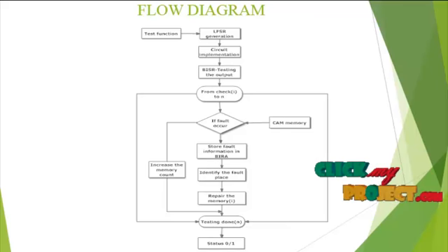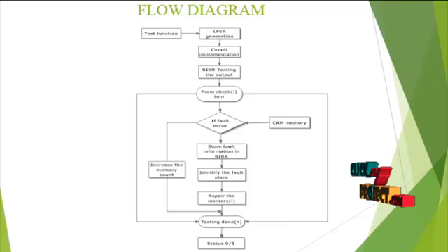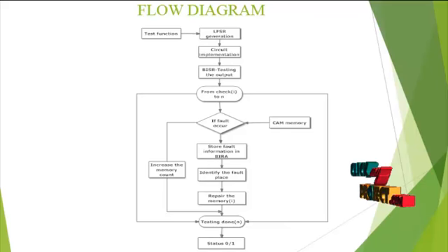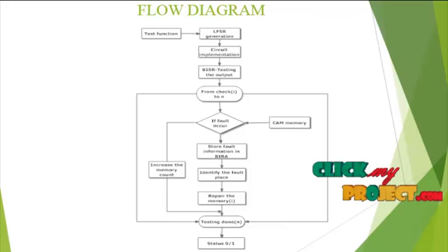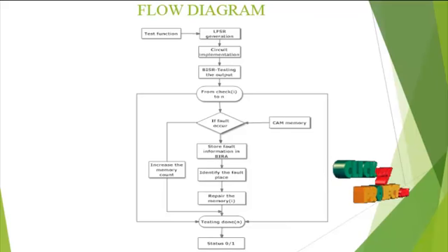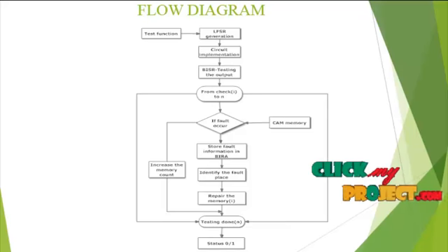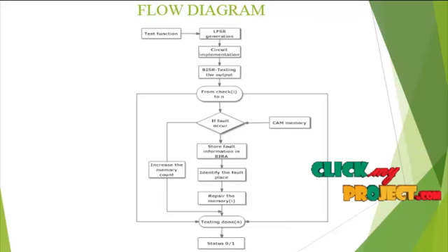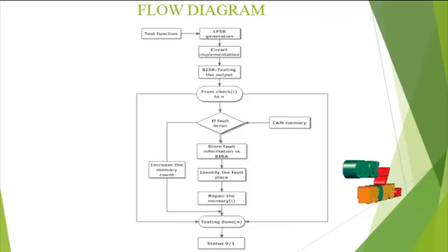After the test is completed or stopped, the signal test_finish is activated and BARA executes the RA process to find repair solutions. The BIST unit consists of the test pattern generator, test address generator and the controller. The built-in redundancy analysis unit consists of a counter, multi-fault detector, fault storing content addressable memories and the repair registers with the CTR.